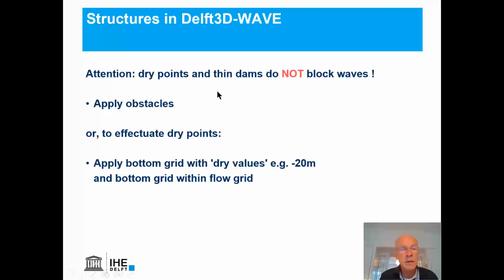Structures in Delft3D wave, you have to be careful using dry points and thin dams. They're not automatically transferred to the SWAN model, so you have to apply obstacles for that, or you have to include the structures in your bathymetry.